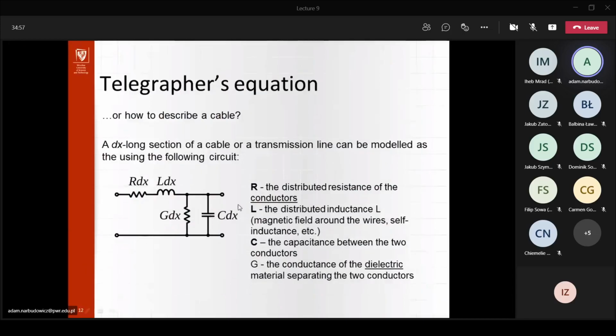But again, the phenomenon itself represented by this capacitance is also a lossless case, because if we switch the voltage off, then that energy will be recovered from the electric field back into the wire. And again, even though there are some lossy components in practical capacitors, that is actually represented by the conductance here.